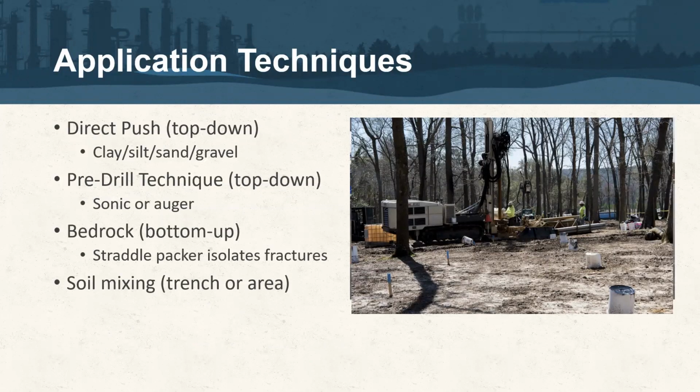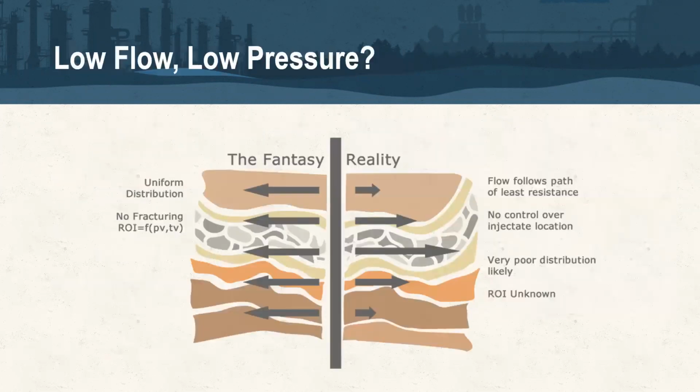As Matt mentioned, anything soil mixing, trenching area, soil mixing, direct contact, that's always going to be the most intimate way to get your product to react with the contaminant. So if you can do it that way, you should do it. But if you're probably on this webinar here today, you're interested in seeing how it's done in situ. Again, we mentioned earlier, these are slurries, so more common injection techniques will not apply.